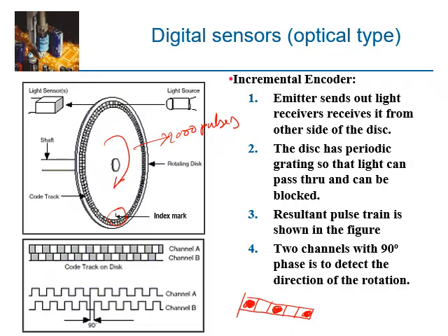So basically you need to have a reference signal that will be detected by the controller only one time in one whole revolution. So once you turn off the machine, every time you turn it on again, in technical terms you have to home, H-O-M-E, the motor, until it detects the index signal.